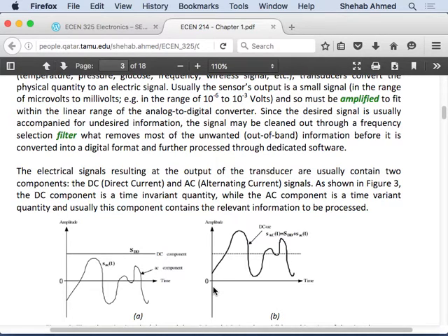So I have a signal here that has a component that is AC and DC, right? If it's not sinusoidal or if it's not pure DC, then it has some AC component. Signals can either be AC or DC. This wiggly signal here has an average value, which means it has a DC component. And it's not a flat signal, which means it also has an AC component.